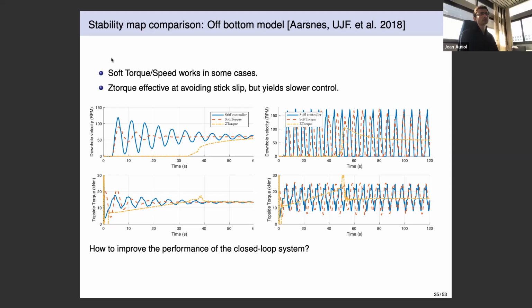So far, we have assumed that the static and kinematic coefficients were uniform along the drill string. Actually, we even lump most of the friction at the BHA, which we know is untrue, but in the estimation procedure, we have to lump everything at one place. But what we haven't tried to do was to change the location where we assume the friction is along the drill string. Yeah, this is of specific interest when you have a multi-sectional drilling device with different types of pipe, for instance, and in that case, of course, the analysis becomes much more involved because you have all these interconnected PDE systems. So, yeah, I didn't say it was easy. If it was easy, I'd have done it already.